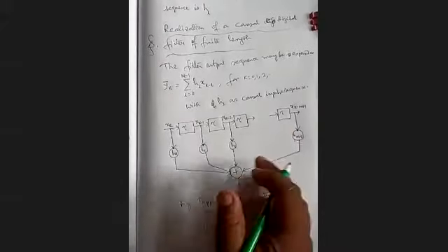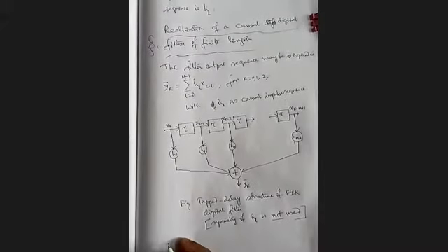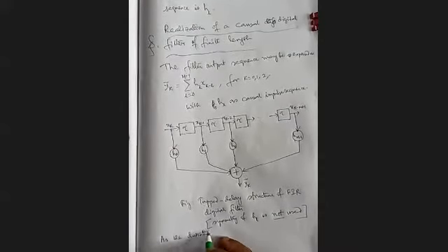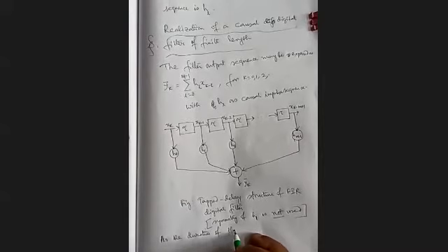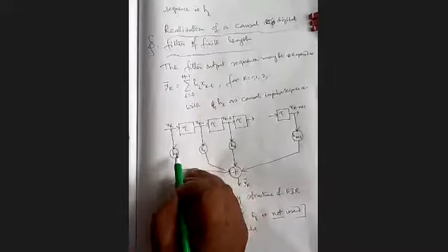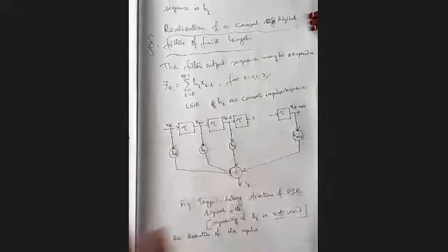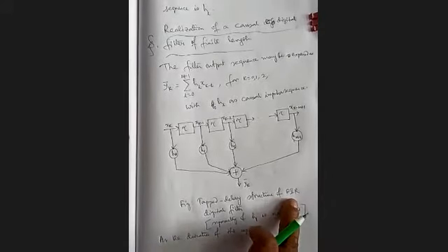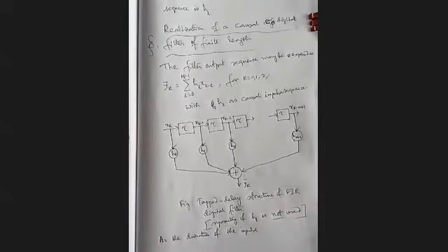as the duration of the impulse sequence or impulse response is finite. So only it is up to h0 to hm minus 1, not after that, up to finite number of terms. Therefore, it is called finite duration impulse response filter.